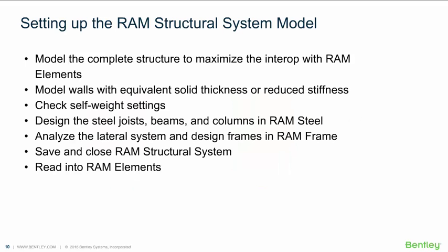One more slide here. A couple closing thoughts on the RAM structural system side of things and getting your model and analysis set up appropriately to get it ready for the import into RAM Elements. You'll go ahead and do the analysis, save the model, close out RAM Structural System, and from there you'll launch RAM Elements and then read in the RAM Structural System file, the .rss file. That's how the interoperability between Structural System and RAM Elements works.